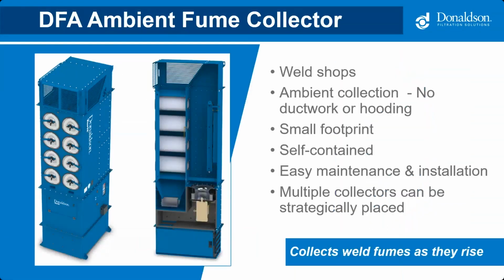The next one on there is our Downflow Ambient, or DFA. Now this is a little different, in that it's an ambient collector, not a source collector. So it doesn't use ductwork or hoods. Instead, it's designed to collect fume from the welding field as it rises. It returns that filtered air near the floor level to assist with air recirculation.